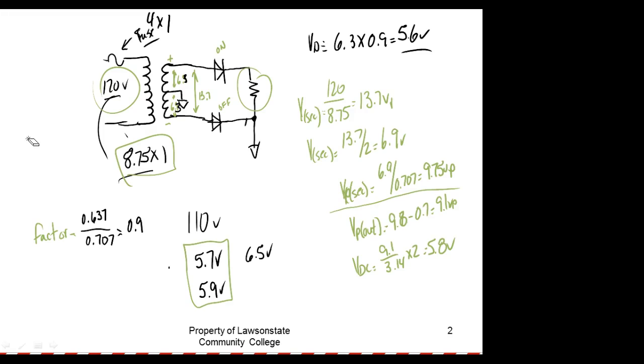So this is why Alabama Power doesn't like to use three-phase transformers. They like to use 3 individual transformers. So it's more to install, but if one of them needs repair, they're not replacing a 3-phase transformer, they're replacing a single-phase transformer that's wired to 3-phase.